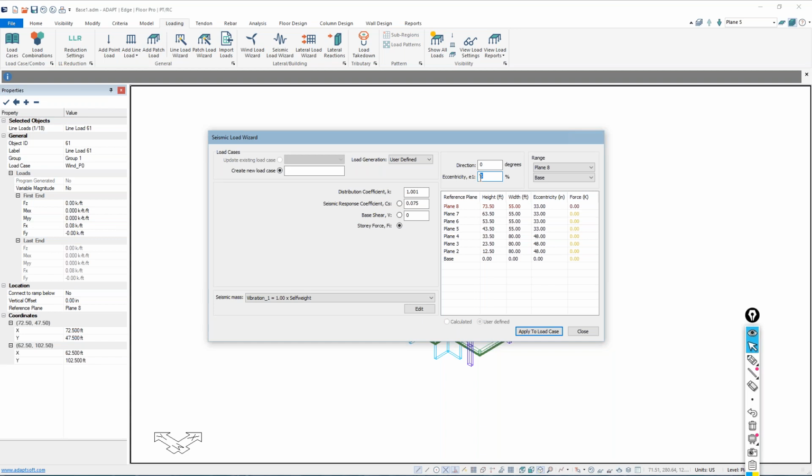You may have to write two load cases, EQX positive and negative, to get plus and minus eccentricity in this case. So again, you could do that in the load combinations, plus and minus. That doesn't really cover all of the cases that may need to be considered for the twisting and the action that would be derived from this eccentricity or the torsion.